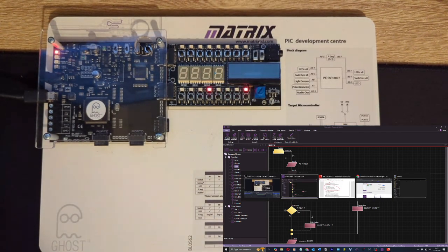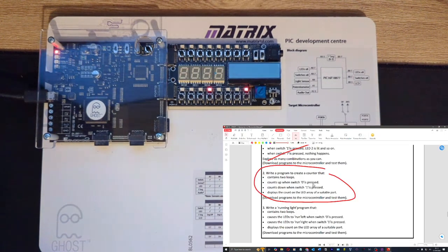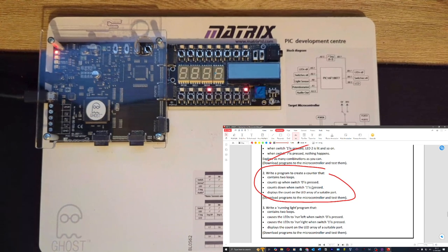Just that delay, but I just wish we had more guidance here. You could just add a line to say, ensure you use a delay to deal with debounce. Remember that the microcontroller will be going very fast, so you want to add a delay after you've read your inputs or something like that.